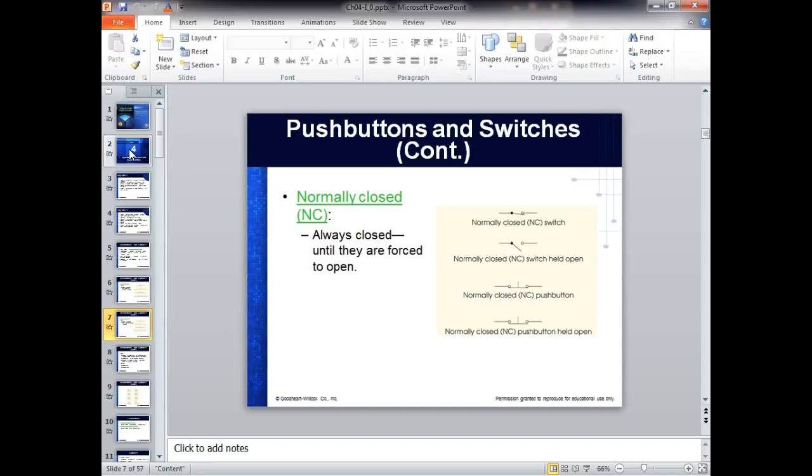The problem is when you buy a DC sensor, they've got to generate the output somehow. So we have several devices that we use as a switch, but the most often used device is something called a bipolar junction transistor, because these guys switch really fast and they can handle a pretty good deal of current.